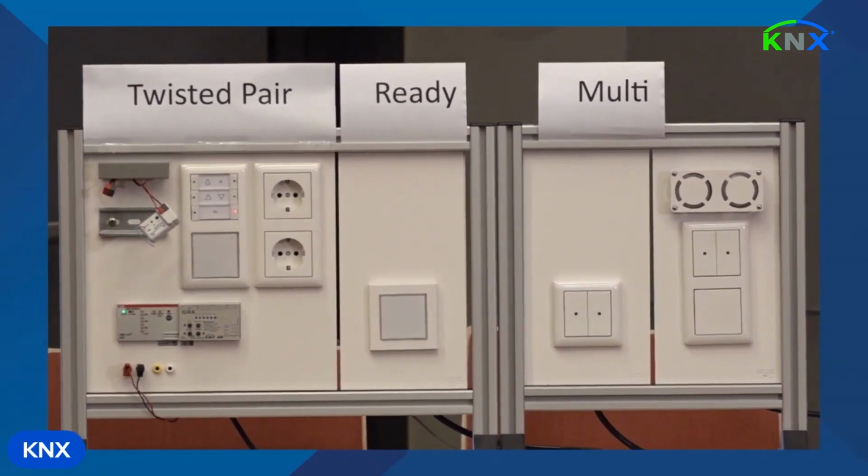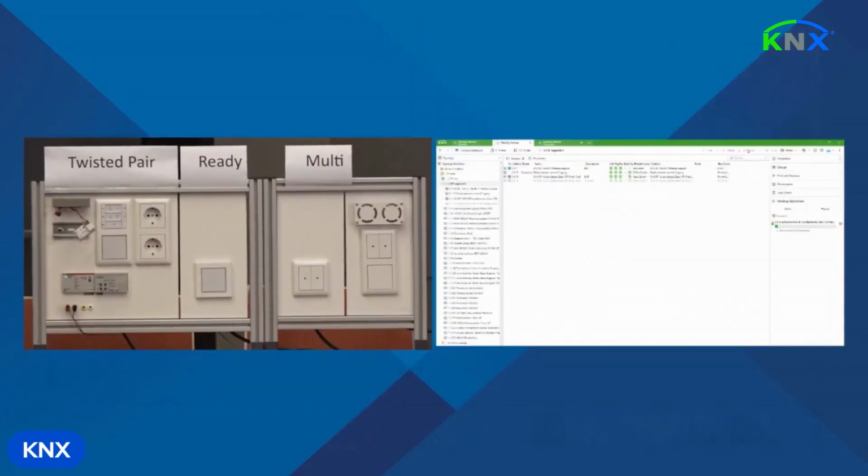But generally, when ETS suggests to program a device, especially when the group configuration is missing, I should follow that suggestion. Yeah, especially for the coupler. And we will see later on one example where configuration on one device has effect on many other devices. We will explain why it's good to follow the suggestion of ETS to then really program all of the devices. I generally always like when I see green flags everywhere here. Everybody likes green flags, indeed, especially in the reports when the project is finished. This is also always what my customers want to see.